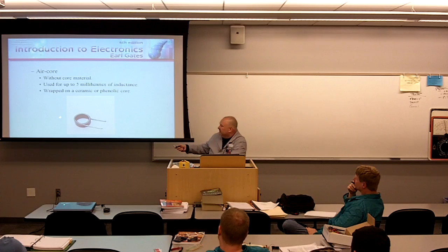A lot of times people see this and think that it's bare wire. It's not bare wire. It's insulated. One of the best ways of getting this insulation off, if you're going to do a lot of this, is with a chemical stripper. Basically it's like a thinning agent.